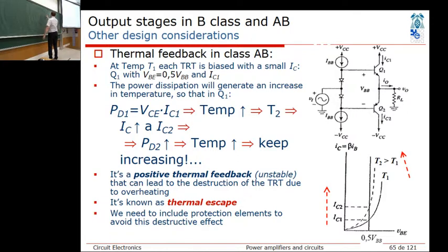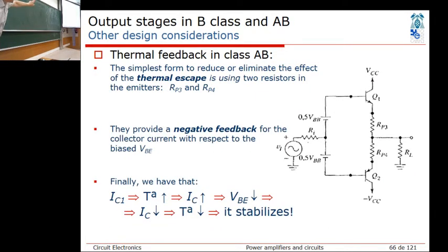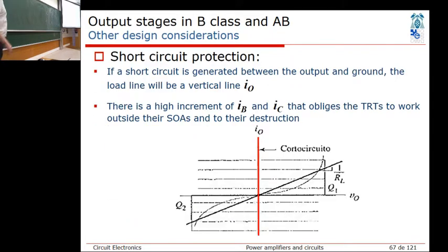Basically, if you run this one high, and also that drop, if you start rising, you can get both of those transistors into saturation if you individually drive those. So it will short circuit between this and that. There's bound to be some smoke coming out of the system. All right, but anyways, that's an easy way to solve the problem.